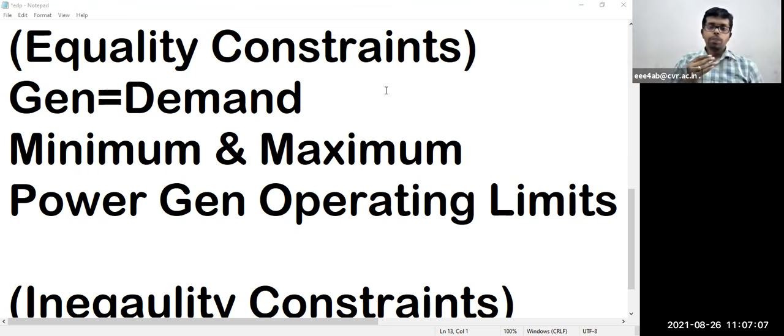The maximum capacity of the generator itself is around 1000 megawatt, but what we are doing is overloading the generator. We are increasing the speed and generating maximum power up to 1020 or 1030 megawatt, like that. We are running 30 megawatt more.